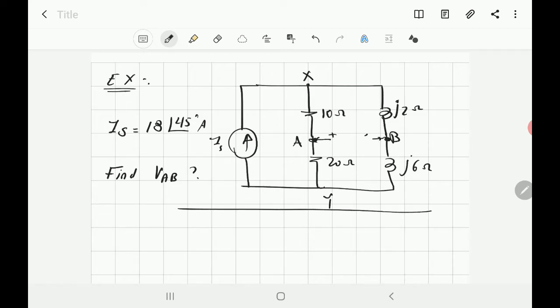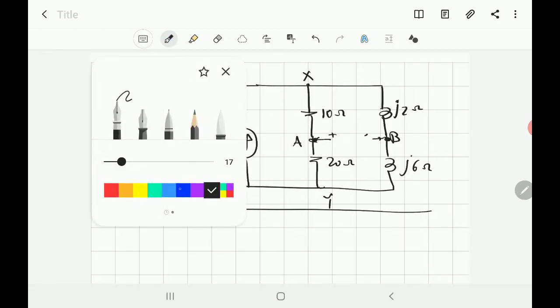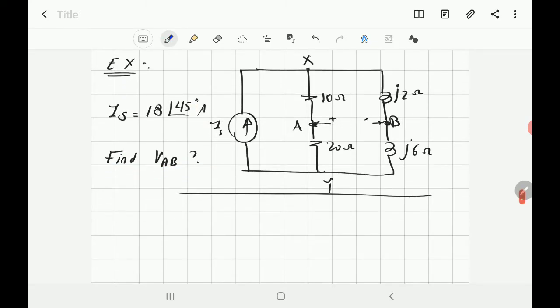You want this voltage here. Okay. Well, to find the voltage VAB, it's not across any element, it's just between 2 points. So once you have something like that, you start to think about Kirchhoff voltage law. To apply Kirchhoff voltage law, you got to apply it in any loop. So you got two loops. You get one loop here in the top and another one in the bottom that include AB. Which one you choose, it doesn't matter. For me, I will just choose the one in the top.